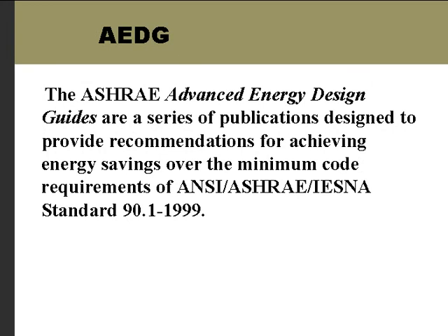And all the subsequent guides have used that as the base standard, and many times the question has been asked, well, why not update the standard to the 2001 or the 2004 standard? The reason that it hasn't been, and that the 99 standard is really still the base, is that was the standard that was kind of in place at the turn of the millennium, and so it's that base case that all of them are going to be judged against. Ultimately, the plan is that there will be some 50% guides. There was some talk of some 70% guides, and then 100% to net zero energy buildings. So that's why it was based on the 99 standard.